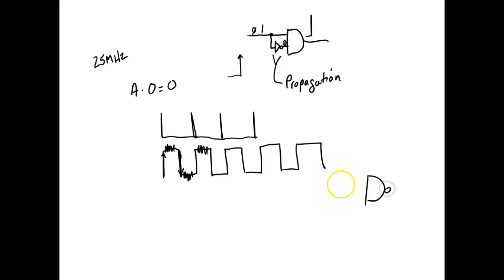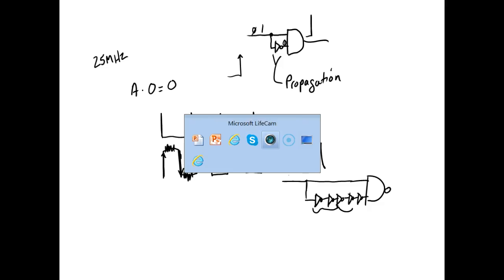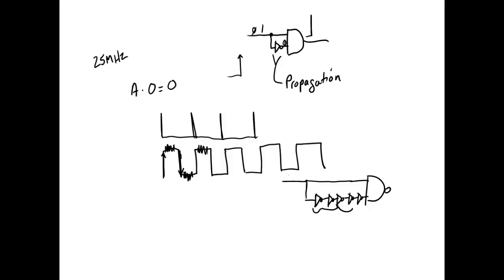So the circuit I've got up here, so we can definitely see this, and I'm using a NAND gate. I got a string of 5 of these things hooked up. So that means I got a really nice delay right here that my scope can pick up. So this is the circuit I have hooked up. This is my edge detection circuit.